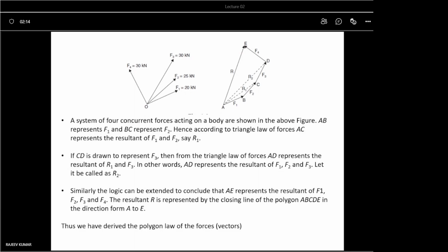Again at point B, draw the x-axis parallel to the point A and measure the angle of F2, and draw the angle from there and make a line, make a ray from that one. Again 25 Newton, so 5 centimeter length you cut it, and again from the point C you draw the horizontal axis, x-axis parallel to the AX or BX, and this will become CX.